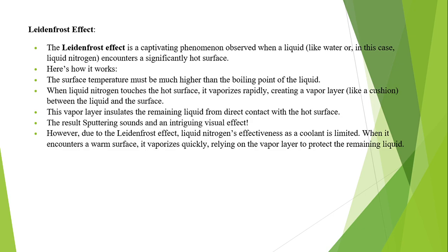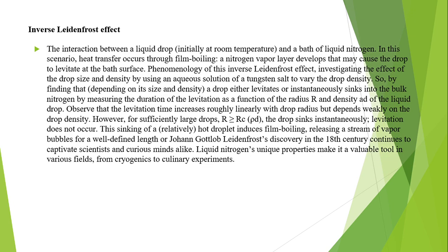However, due to the Leidenfrost effect, liquid nitrogen's effectiveness as a coolant is limited. When it encounters a warm surface, it vaporizes quickly, relying on the vapor layer to protect the remaining liquid. Inverse Leidenfrost effect. This is the interaction between a liquid drop initially at room temperature and a bath of liquid nitrogen. In this scenario, heat transfer occurs through film boiling. A nitrogen vapor layer develops that may cause the drop to levitate at the liquid's surface.